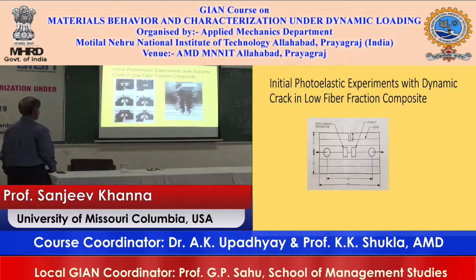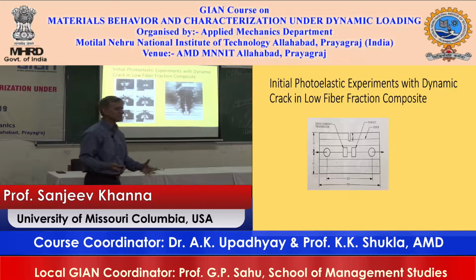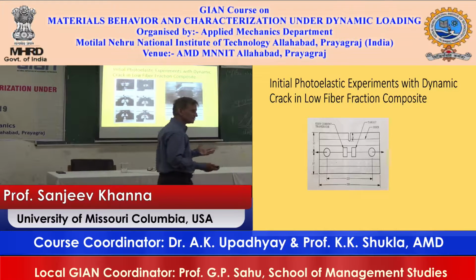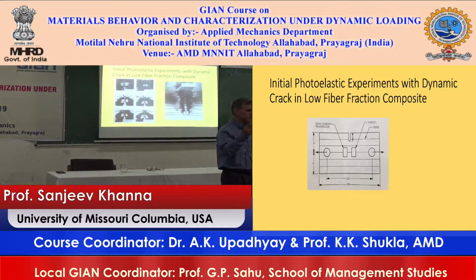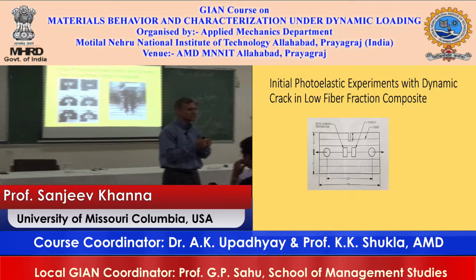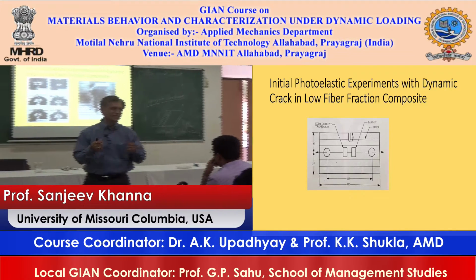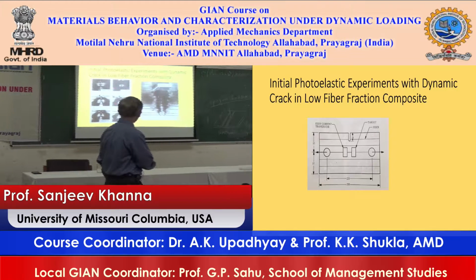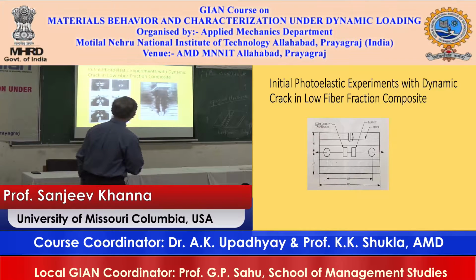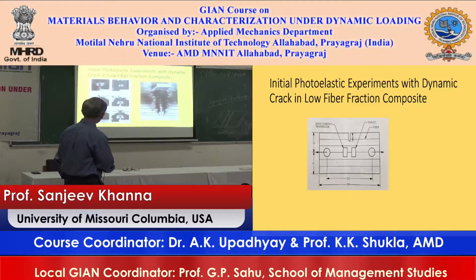Again, this is a photoelastic material. The fracture specimen is made out of polyester, which is very similar to Homalite 100, another type of polyester, and I can see very similar fringe patterns. The crack just started here.